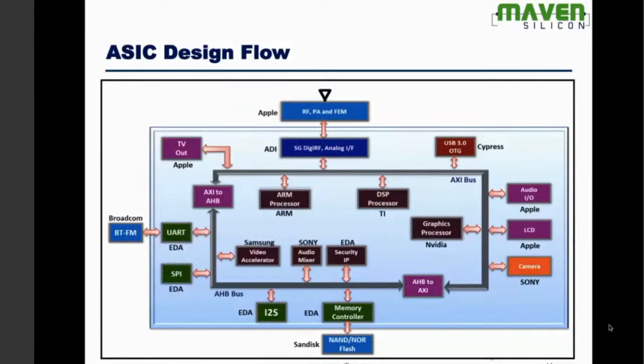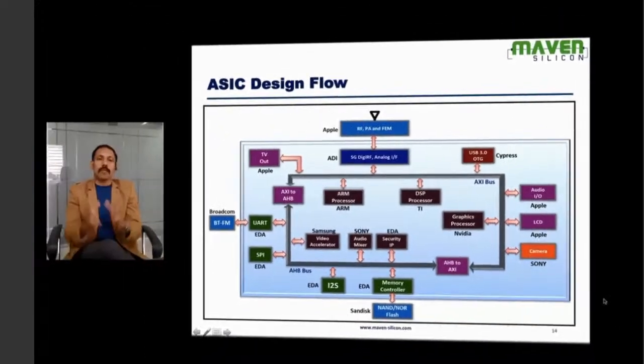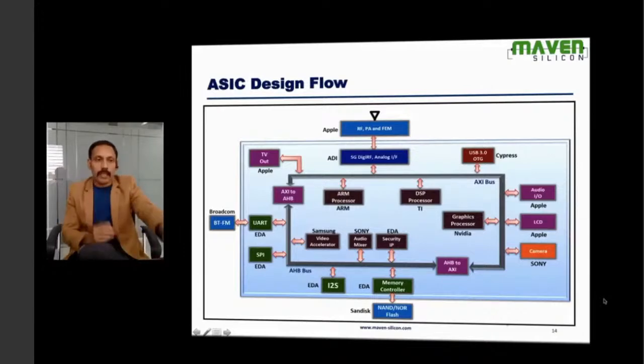Basically, architecture is nothing but a block diagram. You can find all the details like how many IPs would be there and how all the IPs would be connected, something like on-chip bus. And the experienced architect will give the ownership of any particular IP or any particular subsystem to a technical lead. Then the technical lead will create the architecture something like this.